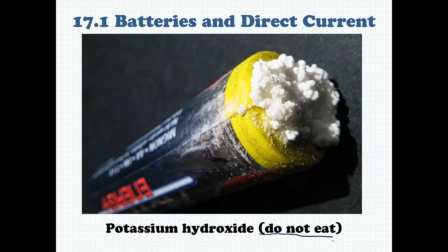It's nasty stuff, but not overly harmful to your electronics as long as it gets cleaned out. And that's why it's good practice when replacing batteries, if you have a calculator, let's say, that takes 4 AAA batteries, and the calculator dies, don't just find the one battery that's completely dead and replace that one. Just replace all 4 and keep 4 of the same type of battery, and that's going to minimize the chance for any kind of weird electrical or chemical things from happening.